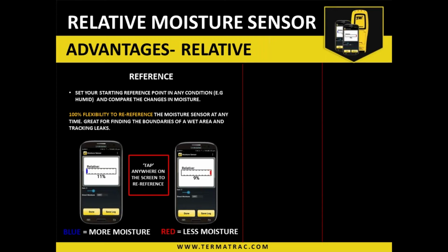Because we want to see peak values, don't move it realistically above 3 or 4, because then you run the risk of filling the box with the red or blue, and then we will not see the peak values. When we're using the relative, we want to know where the maximum area is, so having the gain setting a little bit lower is always better.